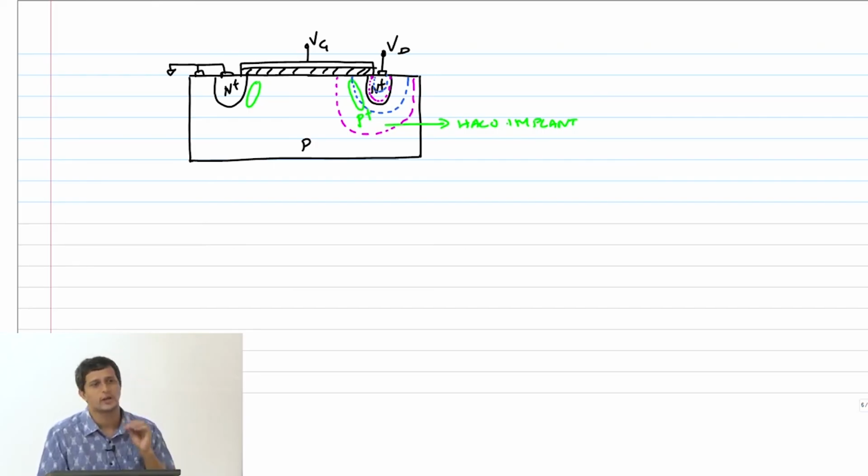Okay, in a BJT, for example, this is not how it is. Physically, it's different. So I cannot actually swap the emitter and collector. It is defined physically and in only one way. Whereas for an NMOS transistor, that's not true.